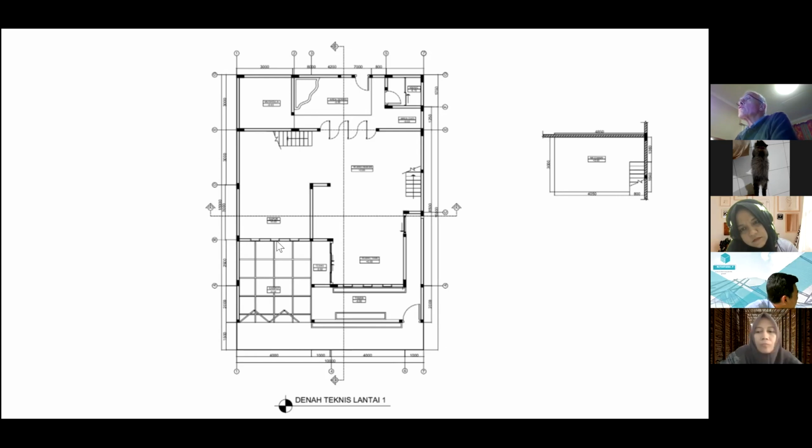Well, this wall is not strong because of all the penetrations. There's a little bit of wall here, but it's so short, it would be very weak. And so this column has no strength in this direction. This column has a little bit of strength, but this column has no bending strength because it's like a practical column. So really, on grid line B, there is no resistance.